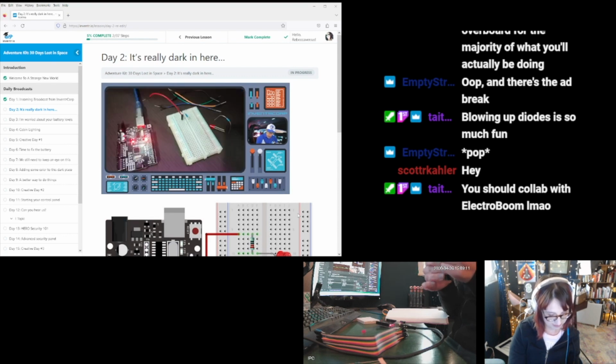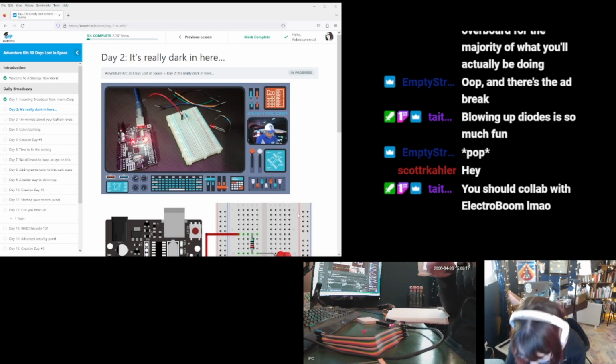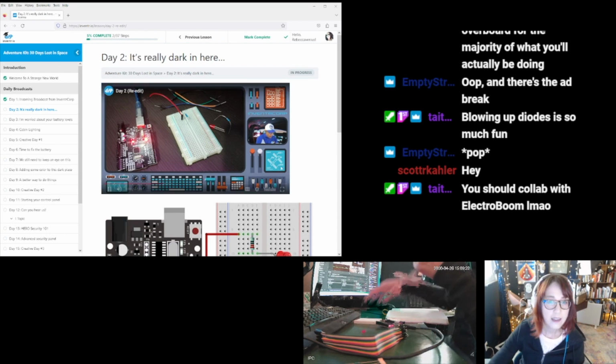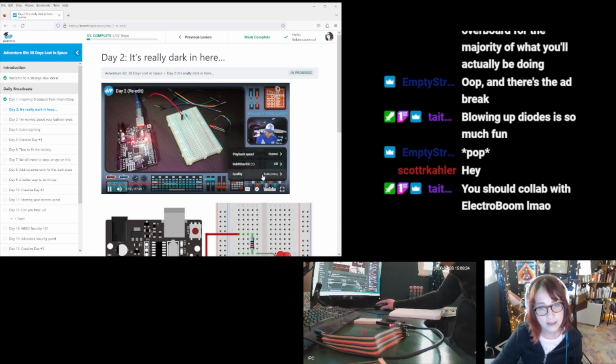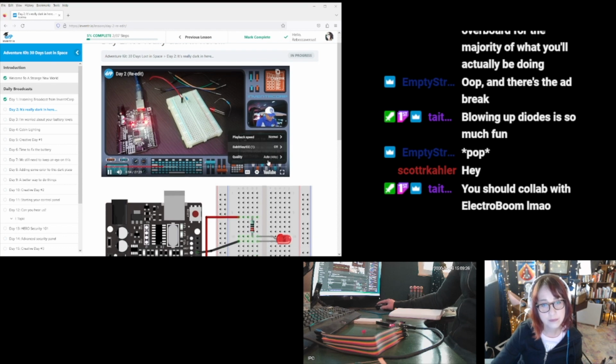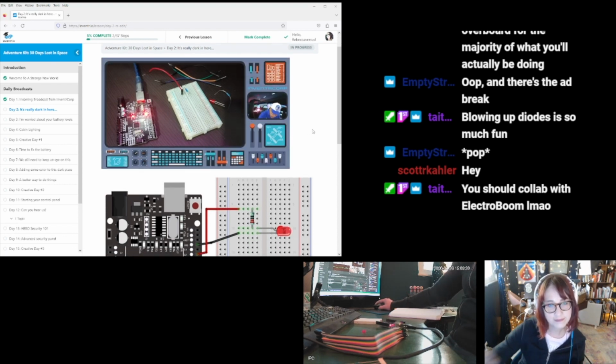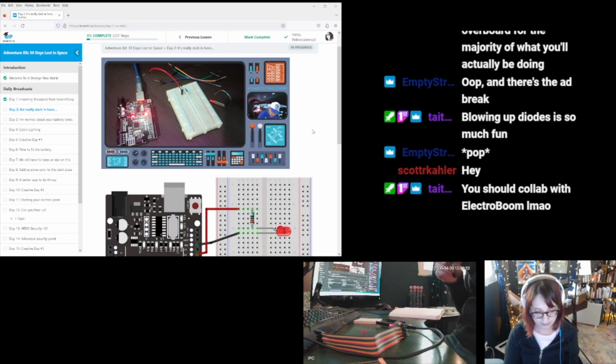So, the breadboard here is there to make this job much easier, because instead of having to permanently solder components together, we can just connect parts together end to end by pushing their ends into the holes on the breadboard. The pins of our components fit right into the holes of the breadboard.